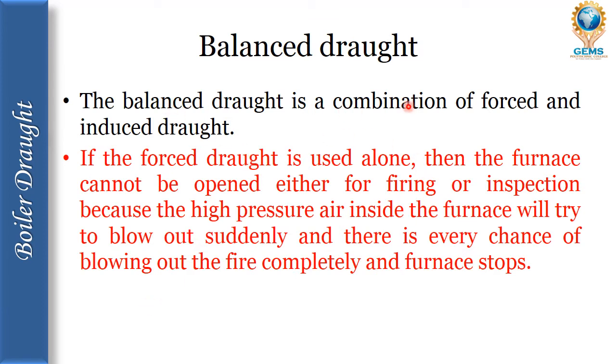Now let's come to the balanced draft system. The balanced draft is a combination of forced and induced draft. If the forced draft is used alone, then the furnace cannot be opened either for firing or inspection, because the high pressure air inside the furnace will try to blow out suddenly, and there is every chance of blowing out the fire completely and the furnace stops.